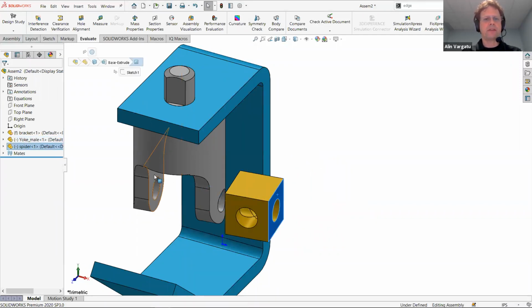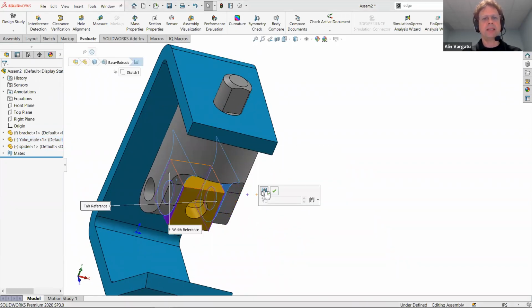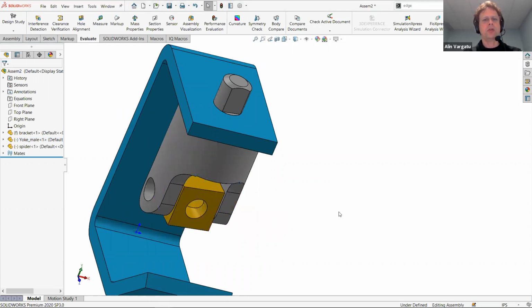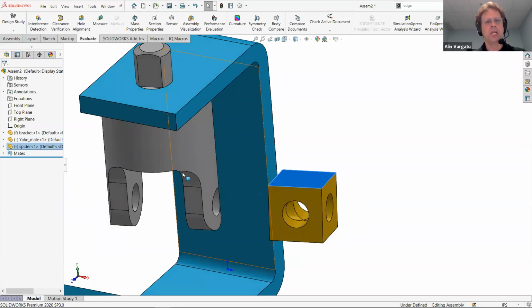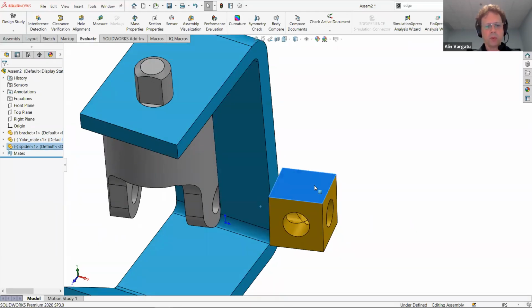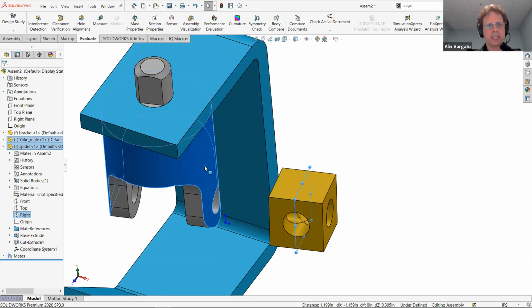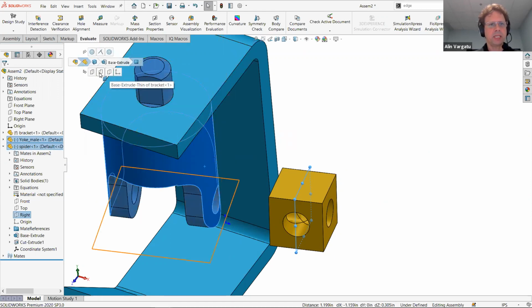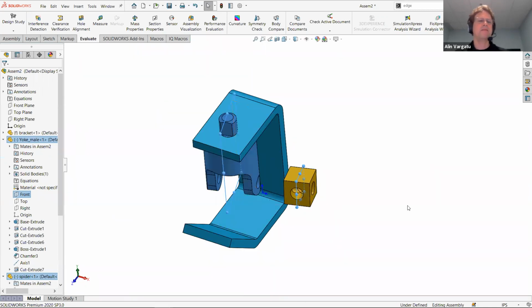And I know you guys are familiar with the width mate, right? So I can select these 4 faces and apply the width. But also because you are power users, you also know that the width mate can slow you down on large assemblies. So you might prefer to use the planes. Now, when I say breadcrumbs, right, I can go here and try to find out the right plane. So that's one plane, hold control, select the other face, but the breadcrumb doesn't come. Maybe it does for the second face, can I do it? Let's see if I can do that. Yeah, so you can do it maybe, but it's very convoluted.